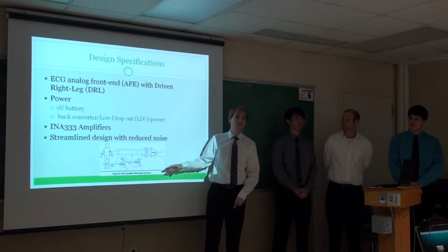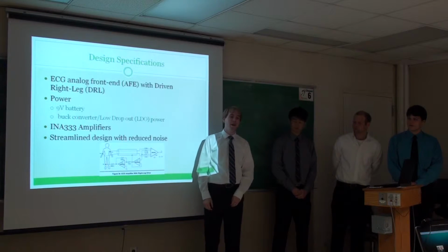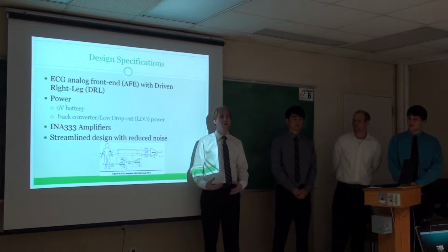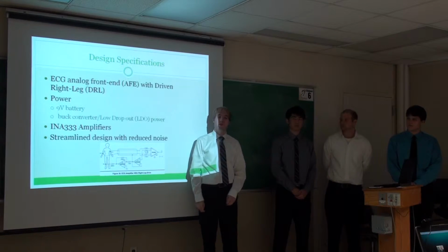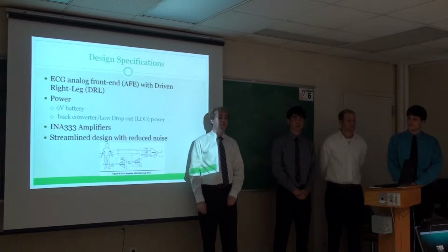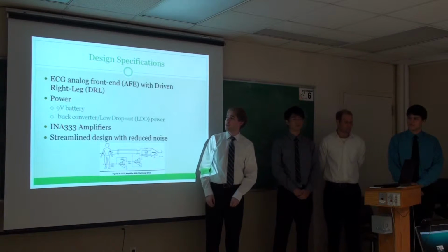And then the entire output is used to reduce small or common mode interference. And the reason it's made for common mode interference is because that's interference that's coming from the system itself. In this case, the system itself is the patient or the person being hooked up to this machine. And those are very small, possibly the millivolts that we're measuring. So we're using this type as our actual way to get rid of that interference.